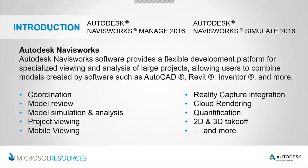So basically it gives us the ability to fly through the model in a much more efficient manner. Navisworks actually rasterizes the geometry, only rendering information that you need to see when you need to see it. So not only do we have the opportunity of reviewing our geometry from Revit and Inventor and AutoCAD, but we also have the ability to do clash detection, simulation, analysis, rendering, even cloud rendering, quantification. Anyway, that's essentially Navisworks in a nutshell.